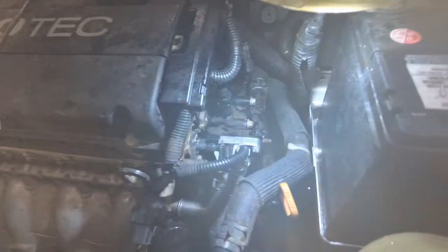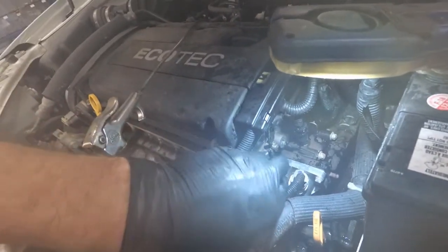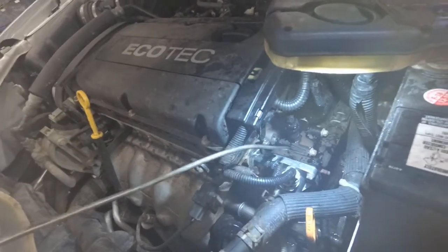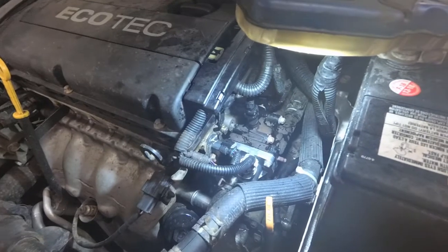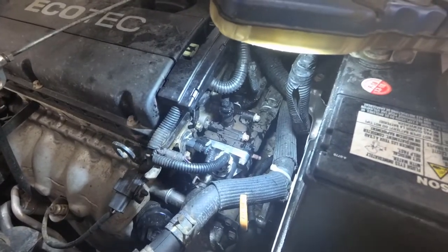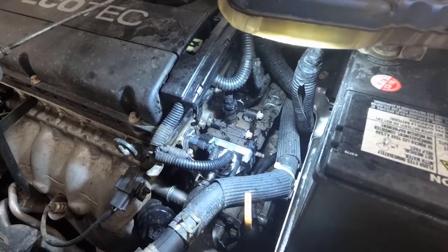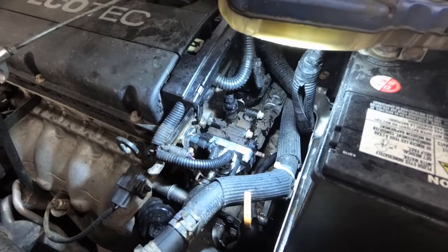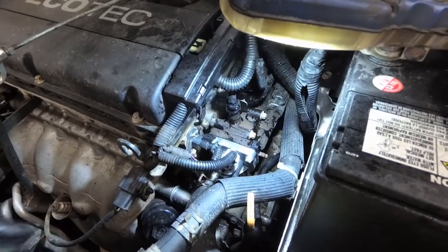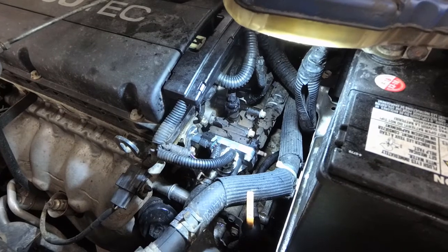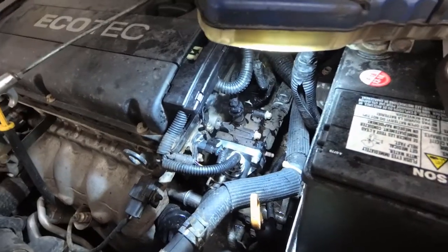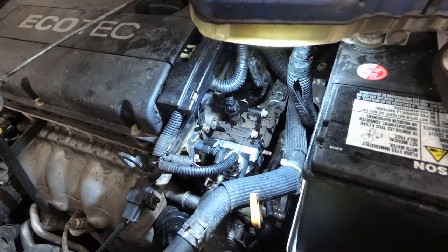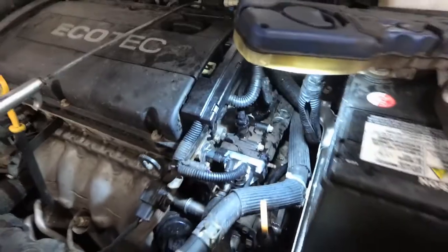Let's shut it off. Well, that plastic thermostat housing is cracked, or the housing behind the thermostat, right in here. There was coolant all over everything before, so it could have been cracked before and I never noticed it. But I'm not completely convinced that the electric cooling fans didn't come on, but then again the radiator temperature wasn't hot enough. Well, it's going to need that plastic housing. That's probably a dealer item.